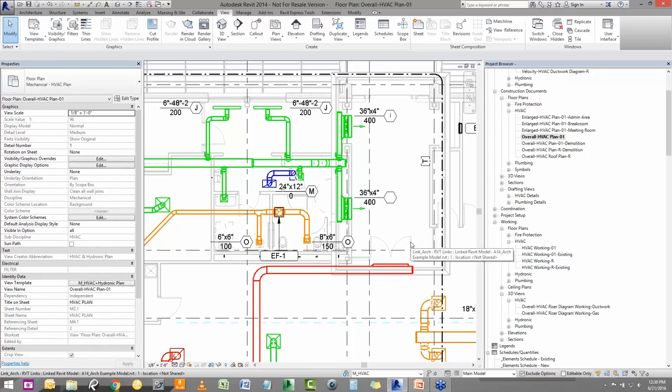It's very important that when we're ripping spaces that we pay attention to some of the settings inside the spaces. We want to make sure that we also rip the plenum space along with the occupied space. A good trick for that is to go into the architect's model, go into an overall 3D view, highlight everything, then use the filter tool to filter out everything but ceilings and uncheck the room bounding capabilities of those ceilings.